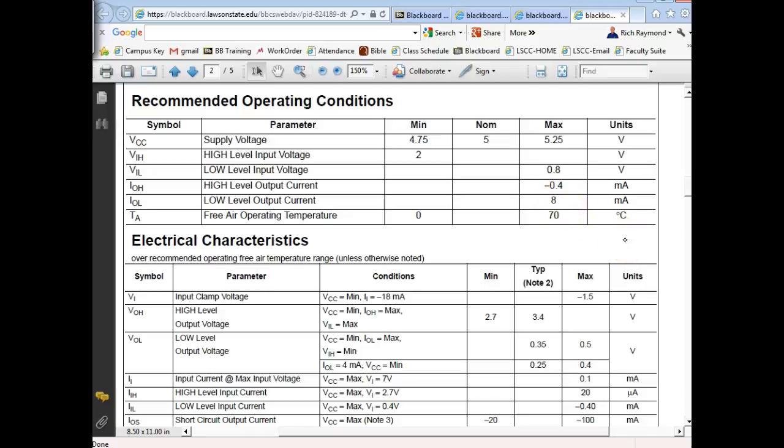Who's going to win the war? The two that are trying to output a high. And it could literally burn up the little sinking transistor on that one guy that's trying to output a low. Y'all understand that?